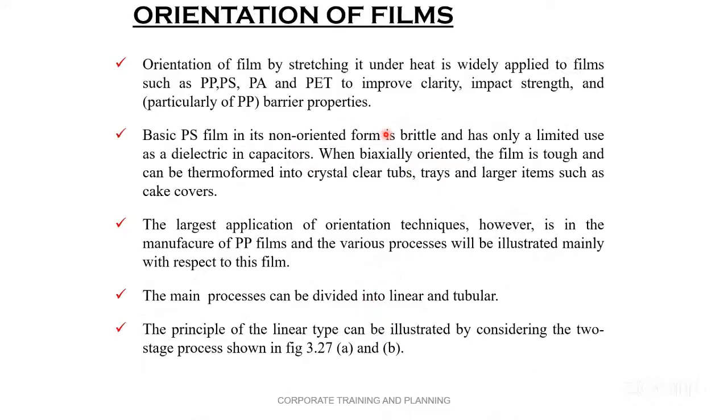See, the orientation of film. Orientation of film by stretching it under heat is widely applied to films of PP, polystyrene, polyamide, and PET to improve the clarity. Therefore, to improve the clarity, impact strength, and the barrier property. Barrier means optical property also.